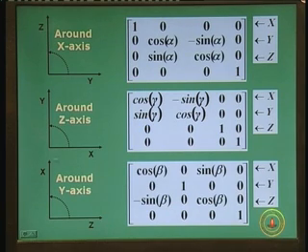Now, if you look at this around the y axis, the rotation which you want is actually z to x. If you want from z to x, not from x to z, to maintain the consistency of positive rotation. So, if you had put the minus sign here, like as in the previous case, you would have forced a positive rotation to go from x to z. That would have violated the principle of right-handed coordinate system, the consistency of positive rotation or counterclockwise, whatever you have studied.